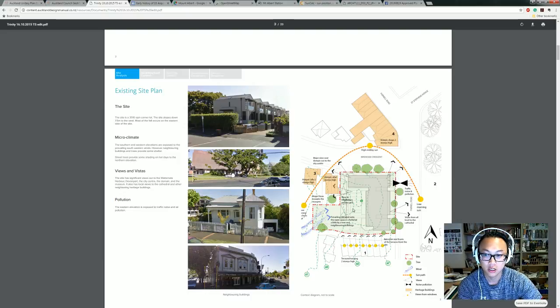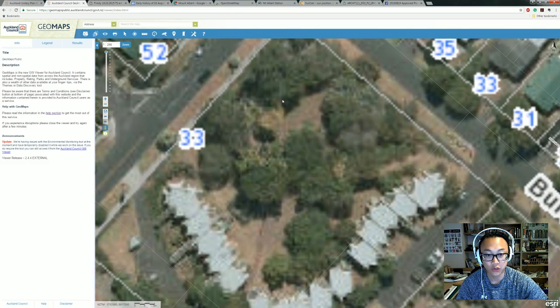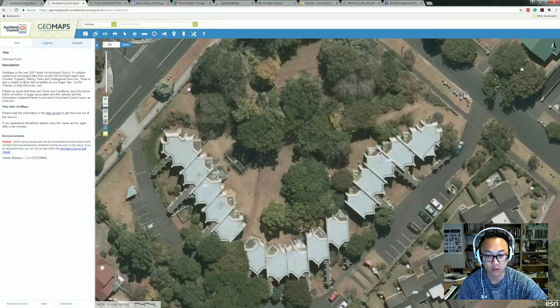the location. Then talk about the climate, so it's mostly about where the sun path is, and this is important because if we start building a 3-story, 6-story, 10 stories, it will create some shadows around, and well, some people might not be really happy that you're doing that. So that's why it's important to have the sun and also the wind. And also on our sites, what's important is the trees, the location of the trees. That's something that you also have to take into consideration.